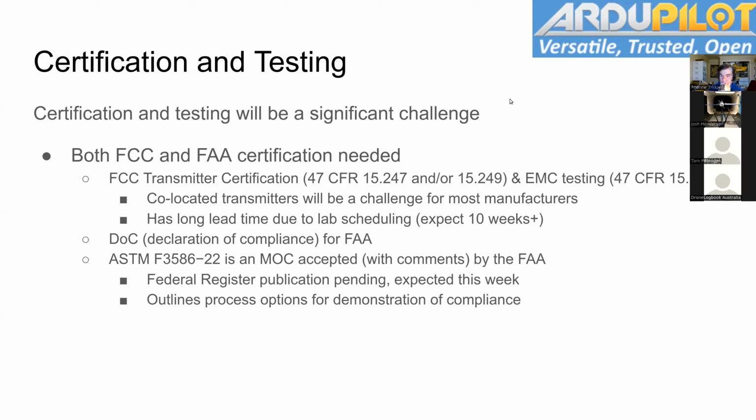So this is probably the largest stumbling block for pretty much everyone here: the FCC, EMC, and transmitter testing requirement. In my experience, having done many products through this procedure, this is a 10+ week thing if you haven't already done it or haven't started it. So this is probably the biggest hurdle here. Then the results of your MOC testing plus your FCC paperwork all feed together to make the FAA DOC.